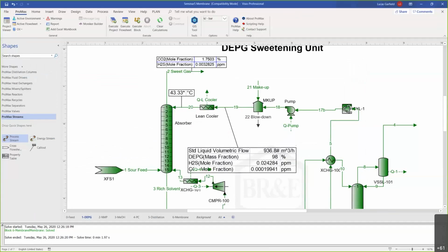So Salman's question, what should you use for capturing CO2, MDEA or DEA? I would say MDEA, activated MDEA is probably the most popular these days. And again, we had that slide where we discussed why MDEA is so popular. It's because it's not particularly corrosive.